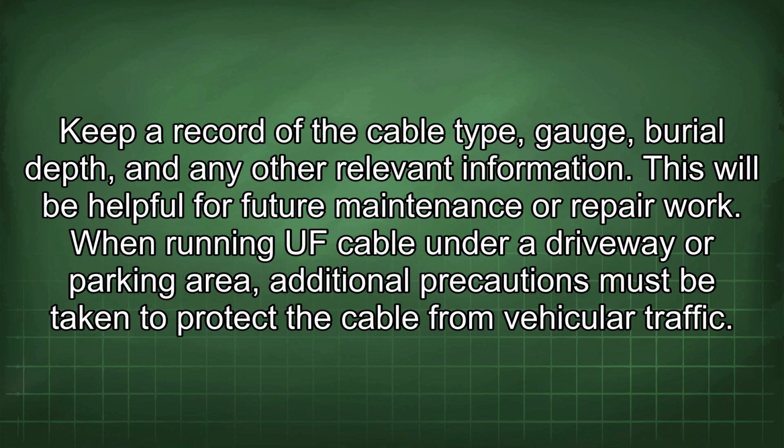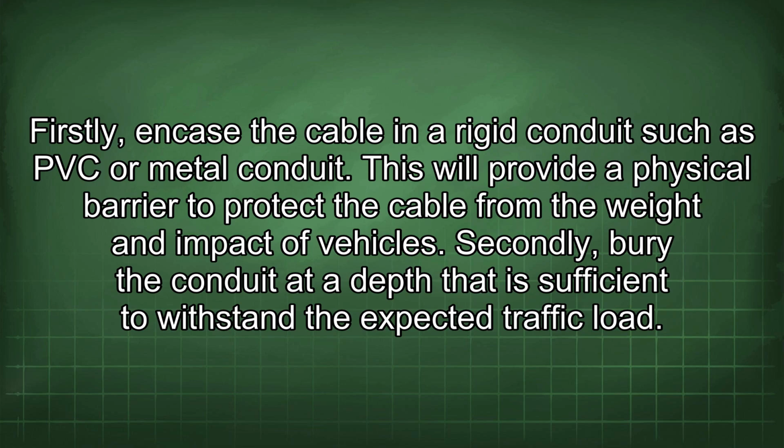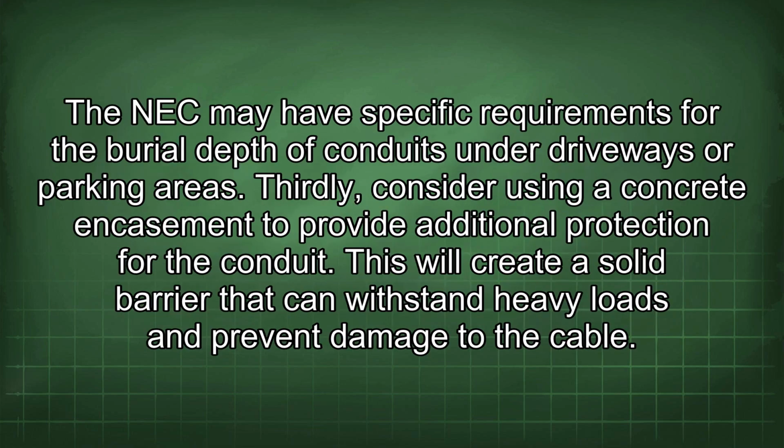When running UF cable under a driveway or parking area, additional precautions must be taken to protect the cable from vehicular traffic. Firstly, encase the cable in a rigid conduit such as PVC or metal conduit. This will provide a physical barrier to protect the cable from the weight and impact of vehicles. Secondly, bury the conduit at a depth that is sufficient to withstand the expected traffic load. The NEC may have specific requirements for the burial depth of conduits under driveways or parking areas.